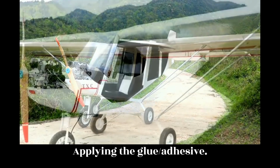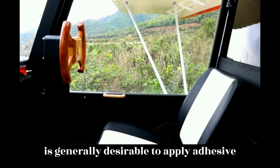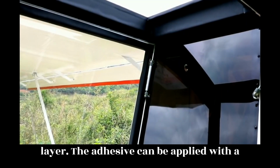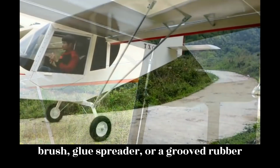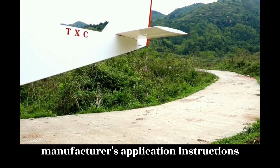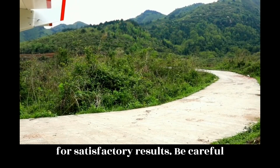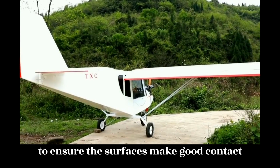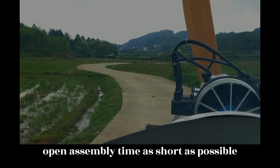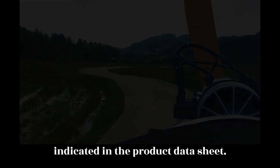Applying the glue/adhesive. To make a satisfactorily bonded joint, it is generally desirable to apply adhesive to both surfaces and join in a thin, even layer. The adhesive can be applied with a brush, glue spreader, or a grooved rubber roller. Follow the adhesive manufacturer's application instructions for satisfactory results. Be careful to ensure the surfaces make good contact and the joint is positioned correctly before applying the adhesive. Keep the open assembly time as short as possible and do not exceed the recommended times indicated in the product data sheet.